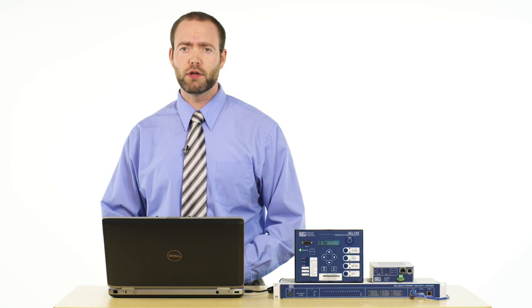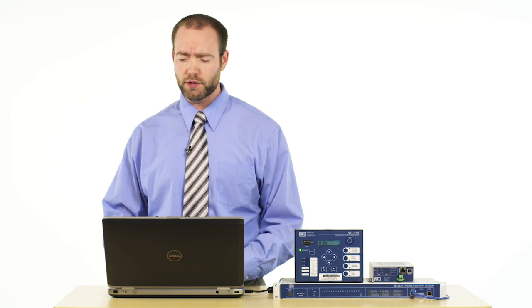If you have some sort of software on your system, such as a legacy piece of software that you need to be able to use through the SEL-3620 proxy, but that software doesn't give you the ability to authenticate using a username and password, we can do that for you and present to that software a virtual serial port or virtual Ethernet port using SEL-3827 Virtual Connect Client. So that's what I'm going to walk through in this video, showing how to use that with the 3620.